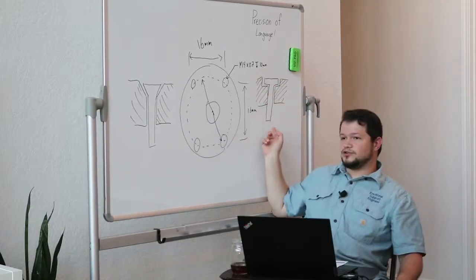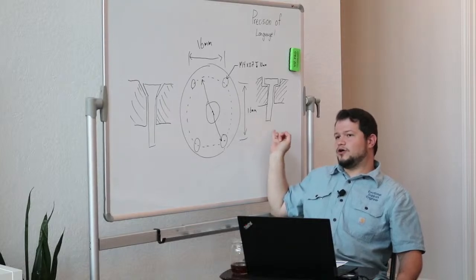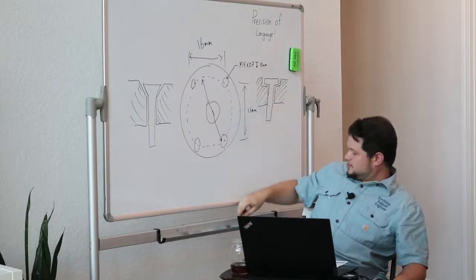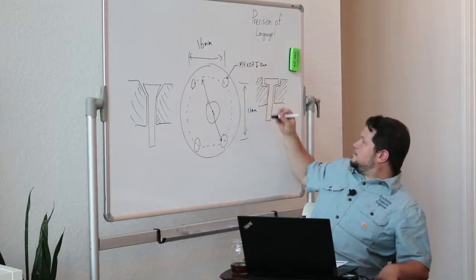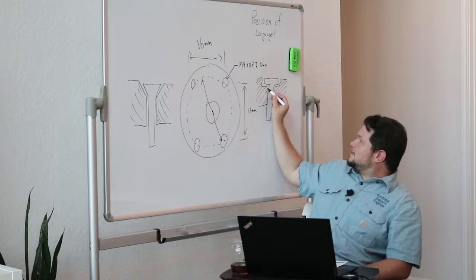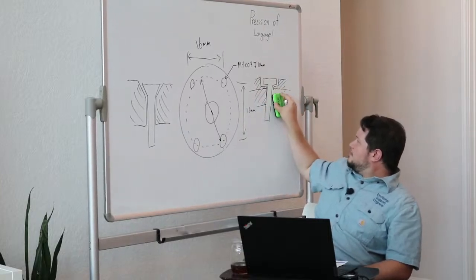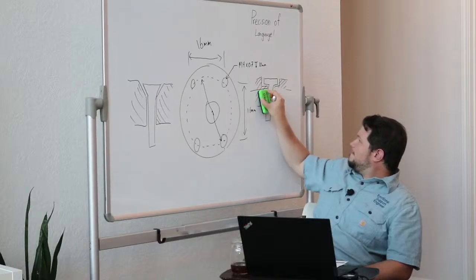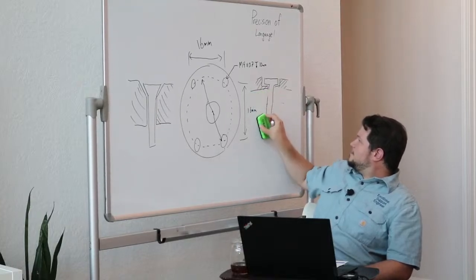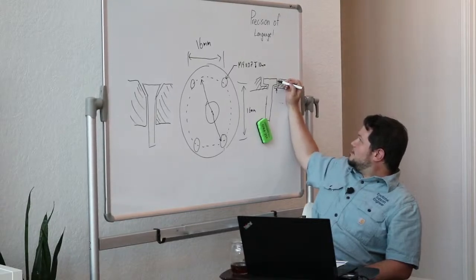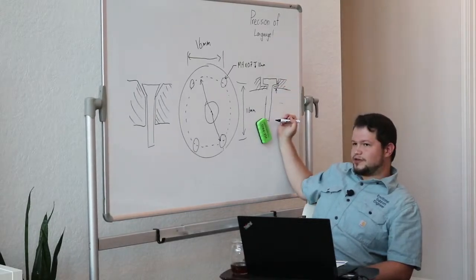So generally, you want to try and use these. You can't always use these. If my material thickness is, instead of being this deep, if instead it was this deep, and this is all I had, that is a very thin area to try and hold all the strength.